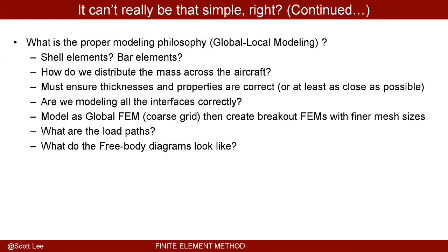Do we want to do it with C shear elements? How about the stringers? Do we want to model them with rods or bars? How do we want to interface? How do we want to conjoin different components? Do we want to hard node them? Do we want to maybe spring them off? These are just a couple of questions you have to ask yourself before starting a large FEM job.